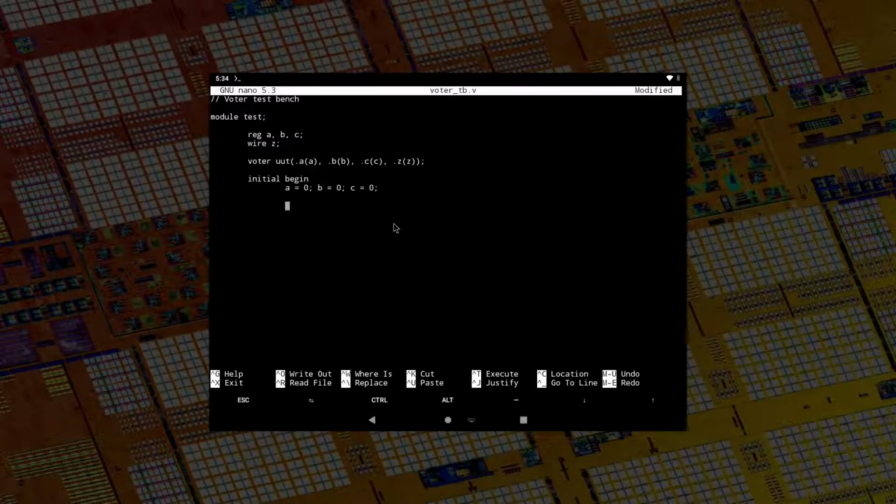We want to print some results. Because we are working with the terminal, the most useful test benches are those that print to the terminal. We can generate waveforms, but we then need a program to show the waveforms. Normally with Icarus Verilog, we will use the GTKWave waveform viewer. It's also included with Termux, but because it's a graphical program, we will need to set up the graphical interface. If you want to try, just go to the Termux webpage